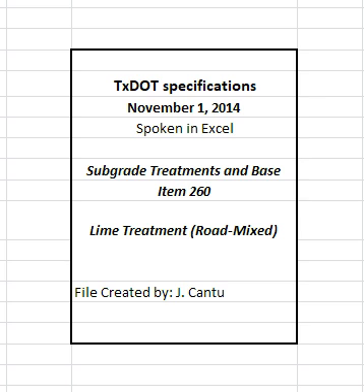Do not surface patch. The 72 hours time limit required for completion of placement, compaction, and finishing does not apply to finishing required just before applying the surface course.